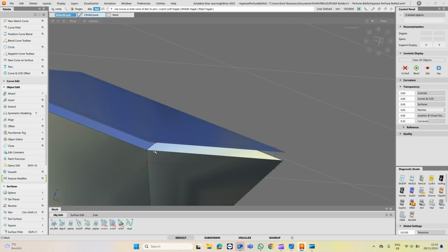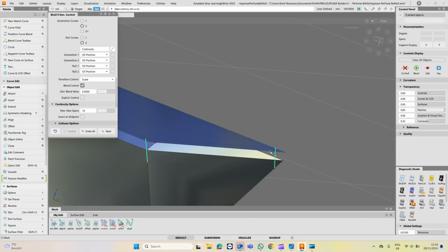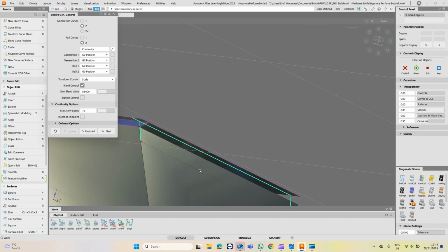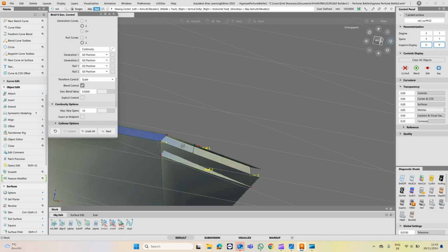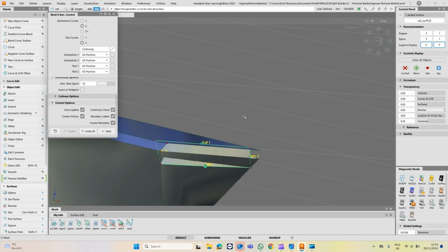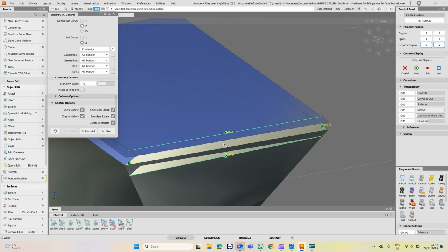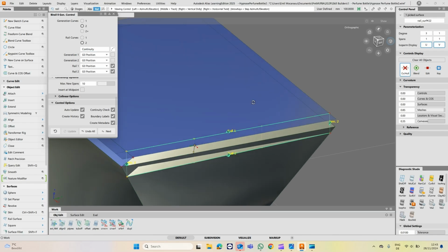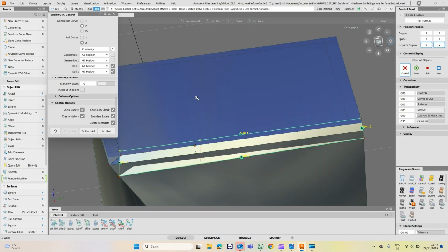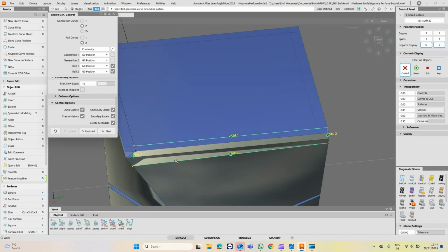And if it doesn't look good, so let's see, that along this curved surface and this one, if it wouldn't be looking good, you would just need to click here on rebuild on the two rails, and it's already better. Rebuild helps clean up those lines. You might get a deviation compared to the curved surface, but it gives you a cleaner surface.